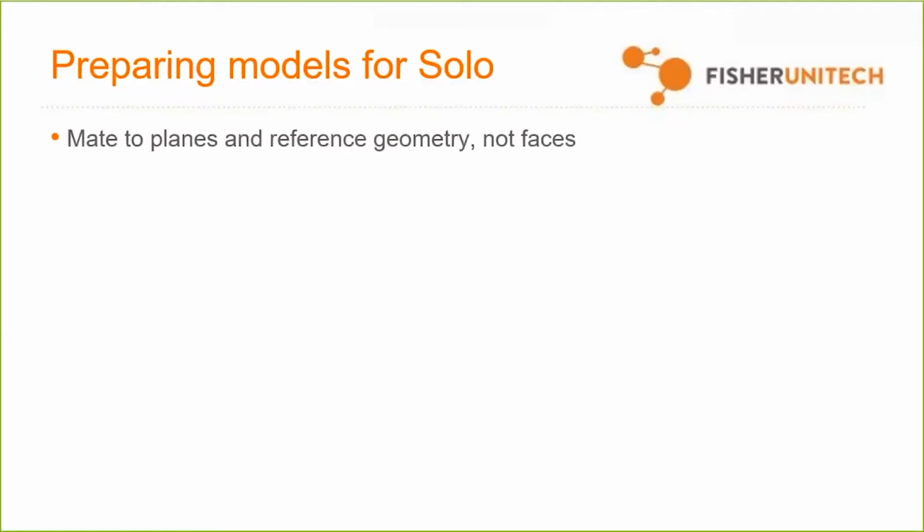Now you guys maybe have gotten an internal ID error in the past. And that's basically saying, well, all right, you told me to swap this model for that one. But when I did, the mates broke because the faces of the one you swapped in don't match the faces of the one that used to be there. You're going to experience the same thing with DriveWorks, because really DriveWorks, all it does is it does SolidWorks' job for it. So instead of you having to right click and choose replace component, DriveWorks does the same thing, but the same rules apply. The internal IDs have to match.